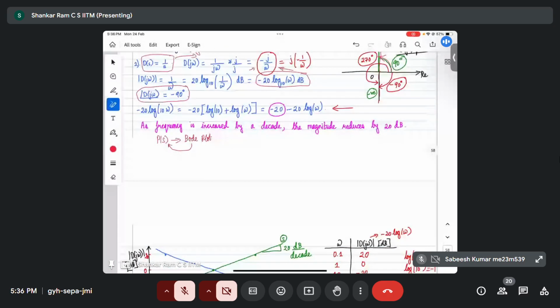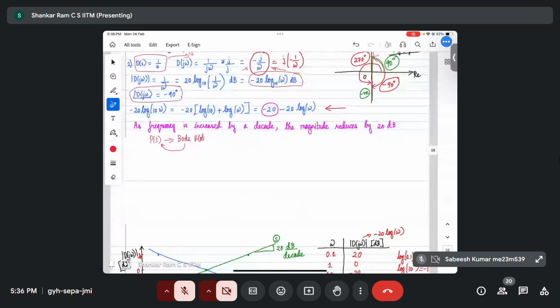You have the Bode plot, you get the P of S. But then, what is an intermediate? You assume a structure of P of S based on your experience, without P of S being a black box, and then use the Bode plot to fit the parameters in the structure. Then by and large, you may end up using only the magnitude plot. I hope that in a broad sense answers your question.